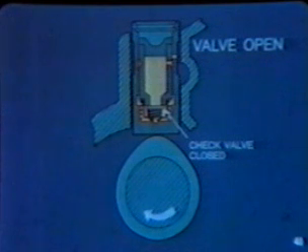Then, as the cam lobe comes up, the check valve is closed by spring pressure to seal the oil under the plunger. The oil is not compressible, so the lifter, in effect, is solid and will move the valve train with camshaft rotation.